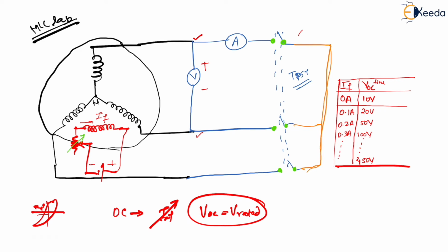Now please tell me, these are all line voltages or not? Yes. Now, do I need phase voltage here? Yes. Why? Because in order to analyze the equivalent circuit, we always use phase, because that is going to be a single line diagram. Single line diagram uses only phase, correct or not? Yes. So let me call it VOC phase.